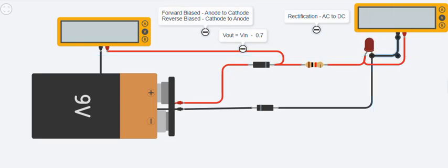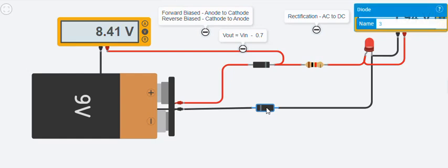Okay. So once you run it, you will see it. You can see that 1.94. So if you subtract 1.94 from 2.5 something, you'll be getting around 0.6, which shows that that voltage is for the LED. Do you understand? Yes. So this is just meant for you to understand. Now you have been able to touch on how to do test points, testing each point in your circuit.